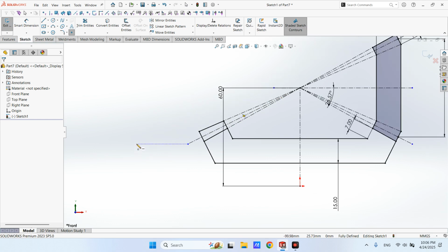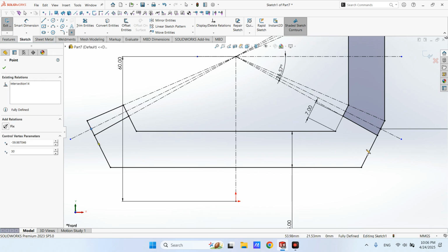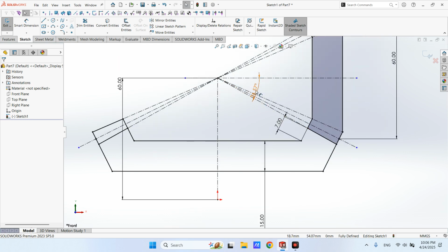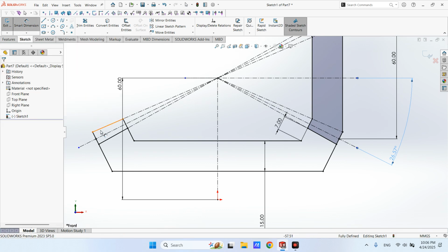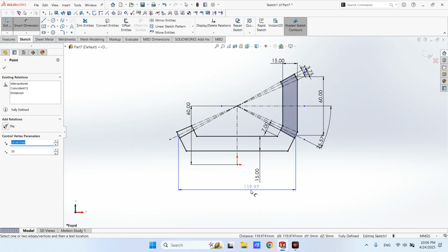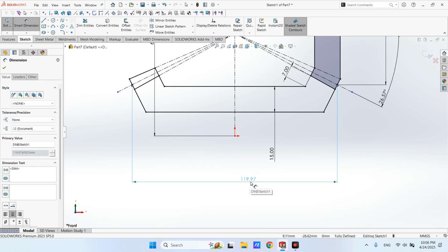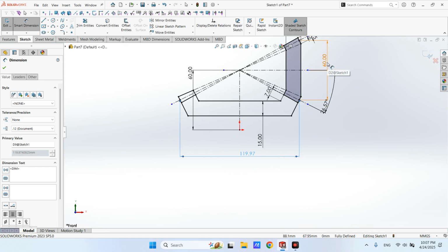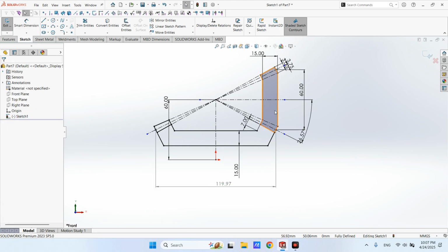And now I want to define the pitch diameter of the gear. I put a line here. Also, this line is here. As you can see, when I define this angle equal to 26.57, the pitch diameter of the gear must be 120, which is almost okay. And also it's a driven dimension. As you can see, it's almost 120, which is 2 times the 60, which defines the speed ratio of pinion and gear. Okay, so far so good.